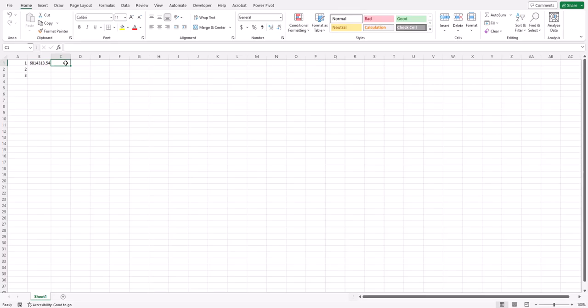For C1, I'm going to put in the easting, 1189761.79. And if I tab, it goes to column D where I can put in the elevation of 26.00. And if I want to put in a description, like this could be nail found in pavement, so maybe NF EP for nail found in pavement, or just nail found. That would be the description, so the field crew knows what they're looking for.